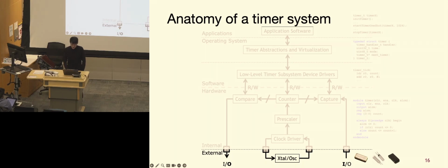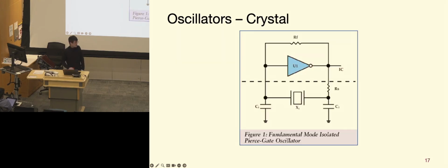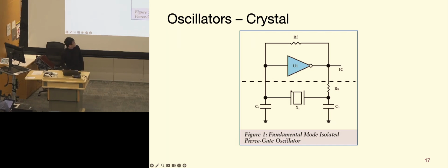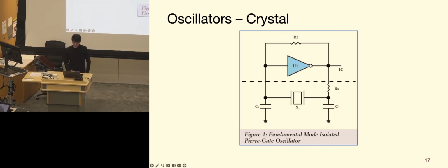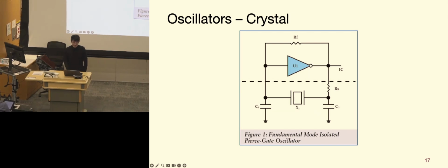We will talk in a little more detail about the crystal part first. This thing here is usually what you would see as a crystal or crystal oscillator. It usually has some load capacitors on both sides. For the values of those, you should just refer to the datasheet. It gives you pretty good references on what load capacitor you should use.